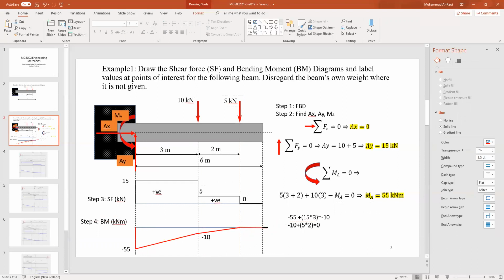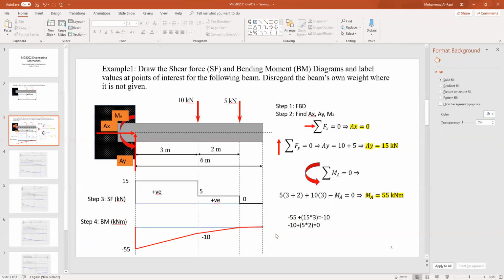When there is no shear force there, it looks like there is no moment acting there. That's how the bending moment diagram representation for this kind of application is slightly different from what you see in general applications. So again, as I taught you before, maybe I need to make this clear now. Even though we solve the bending moments with anti-clockwise as positive, when I do my shear force, it's easier for us to assume that clockwise is positive. Some people could draw this in the opposite direction. And remember, in the bending moment, you could get the same values.